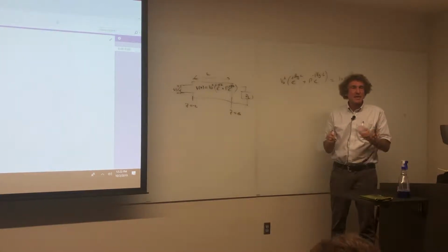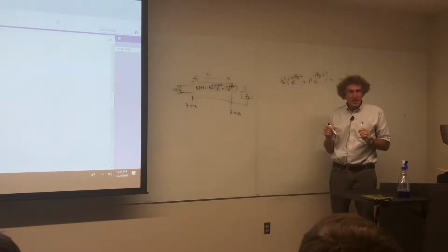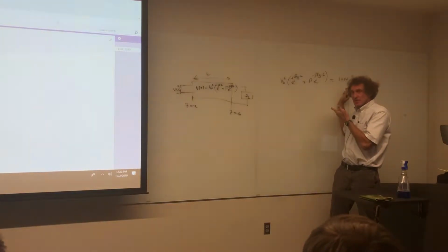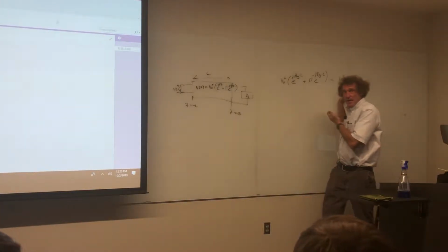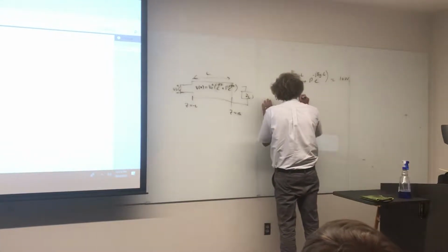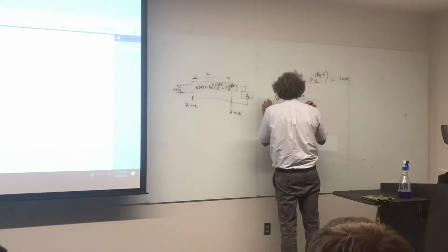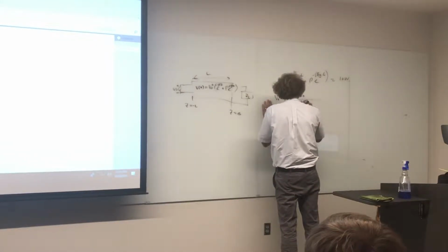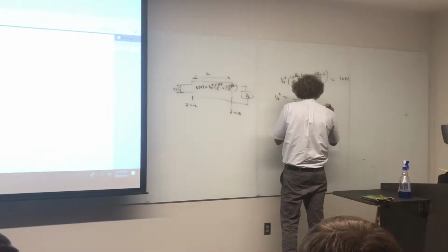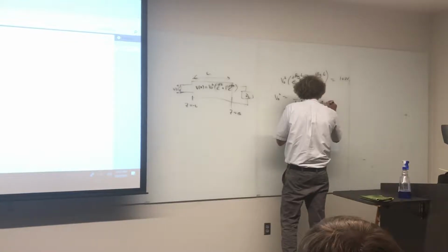Now, a lot of people set up basically that equation, and this bothered me. This equation is something you set up. You solve for V0 plus. Do you all remember this? And I said V0 plus is equal to 100, because that's the source voltage, over e to the j beta guide times L, plus the reflection coefficient e to the minus j beta guide times L.